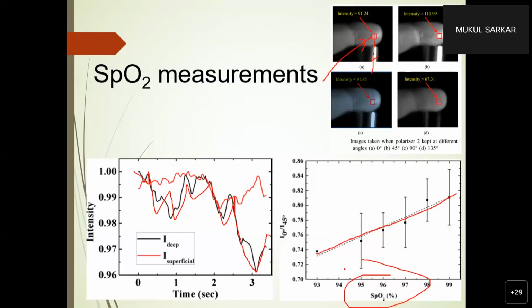The contact devices are not so good, because if hand movement occurs, it introduces a lot of motion distortion, whereas these non-contact sensors are kind of free of motion blur or motion artifacts.